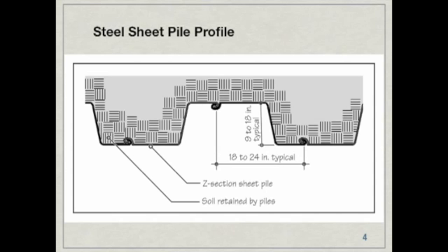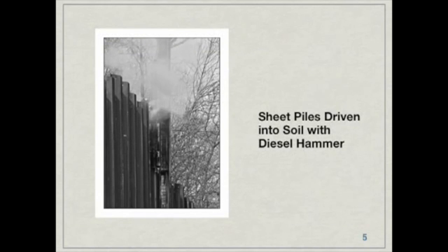For deeper excavations, I'm talking about greater than 15 feet or so, sheet piles are braced with horizontal or inclined braces, or they're anchored with tiebacks. We'll talk about those in a minute. What we see here is a steel sheet pile being driven into the ground with a diesel pile driver.